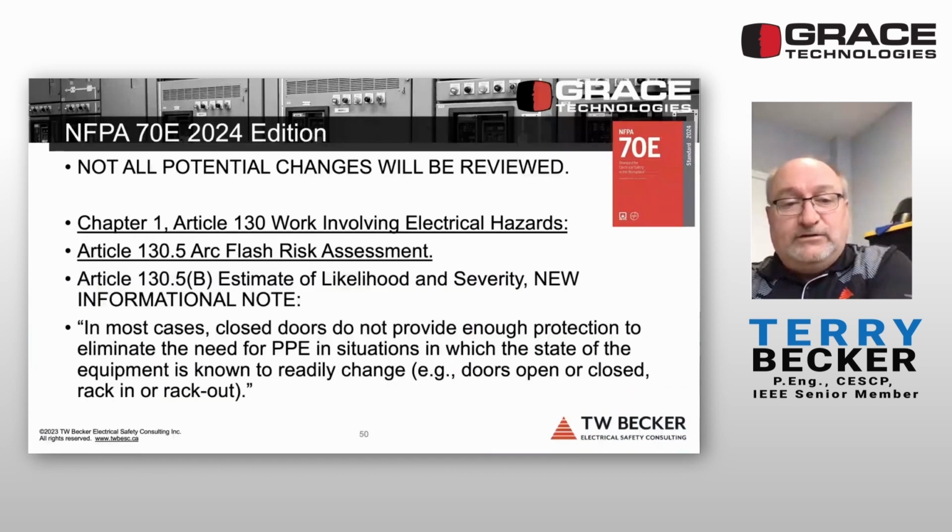Article 130, again, work involving electrical hazards. So estimate of likelihood and severity, new informational note, just clarifying that closed doors do not provide protection. And all along, they never should have been considered.